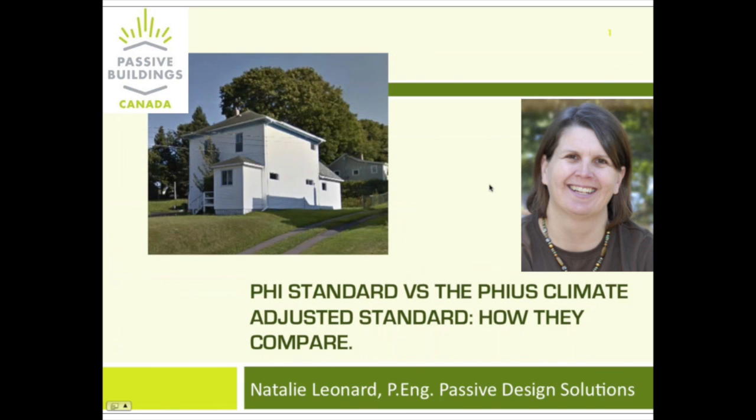I think the final air tightness was like 0.43 on that project, so that helps quite a bit. Because it's quite high density, it's 4 occupants in a relatively small building. So our energy budget was quite good. So we just had electric heat and a hot water heat pump, Energy Star appliances, nothing really special on the appliances, and we reached the PE.